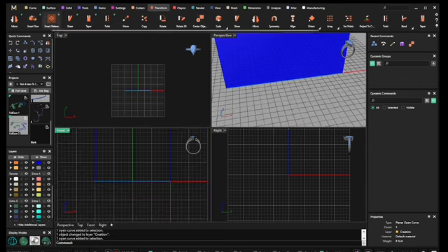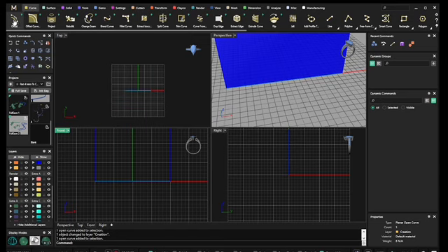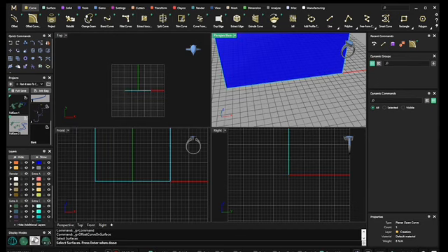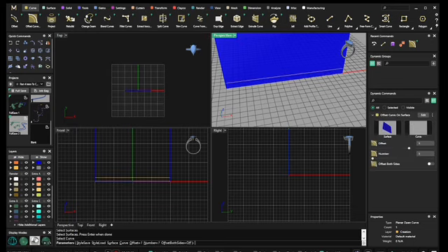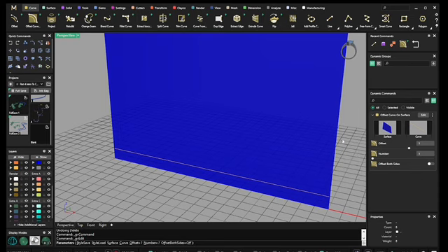All right, my next command under curve is offset curve on surface. I selected the curve, I hit offset curve on surface, and now it wants me to select the surfaces. So I'll select this and then press enter when done. There we go. Okay, so over here in our dynamic command box, we have our surface in the one box, our curve in the other, and the offset is set at 1. That's the default. And so you can move that right over here.